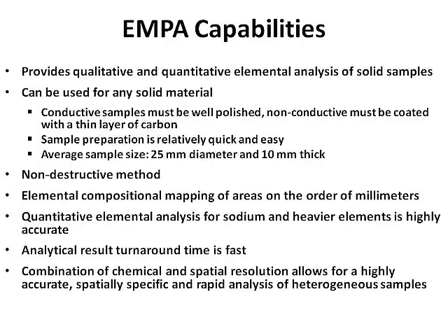So the sample preparation is relatively quick and easy, and the average sample size is a 25 millimeter diameter and 10 millimeter thick disc. It's a non-destructive method, and elemental compositional mapping of areas is on the order of millimeters. The quantitative elemental analysis for sodium and heavier elements is highly accurate, and the analytical result turnaround time is fast. So the combination of the chemical and spatial resolution allows for a highly accurate, spatially specific, and rapid analysis